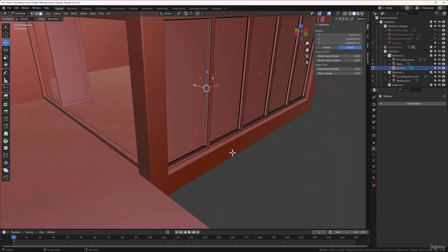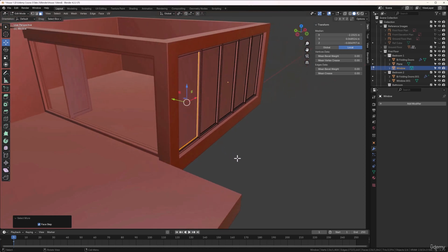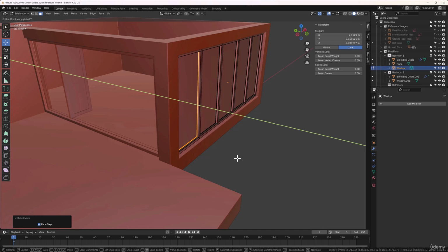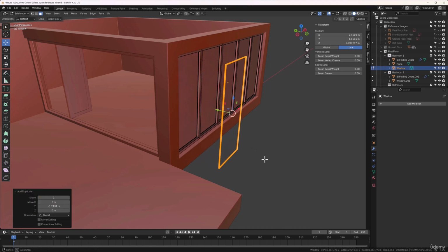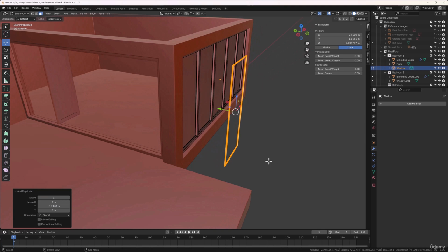And with one face selected, hold down Control and keep pressing plus until all faces have been selected. Once we've done that, let's press Shift D and Y and bring a copy. I'll bring it forward for a moment in the air, in the clear where I can see it, and then I'll press P and I'll separate by selection.